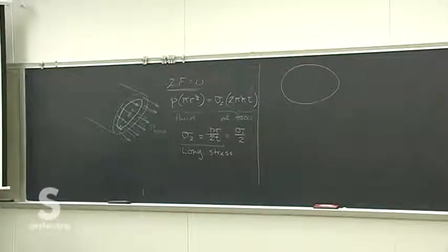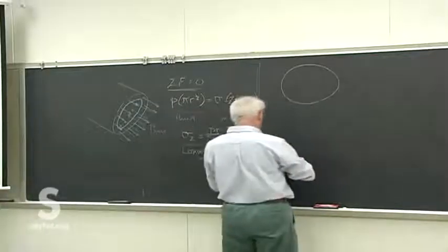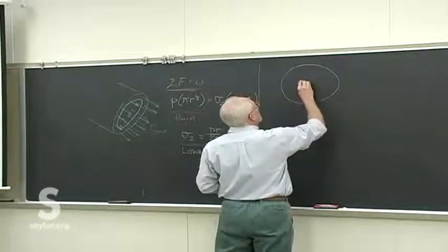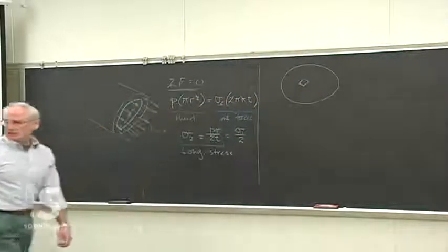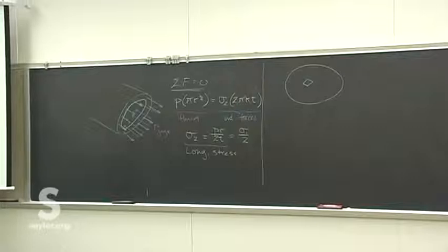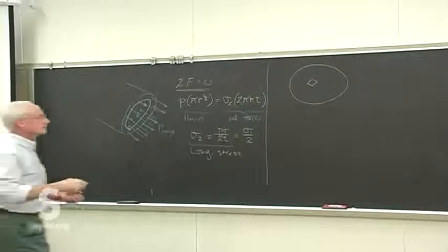Yeah, well, that's a pressurized, thin-walled pressurized vessel, except the atmospheric pressure P is close to zero. Yeah, so I'd like to look at a problem like that. The gauge pressure and the internal absolute pressure are essentially equal.